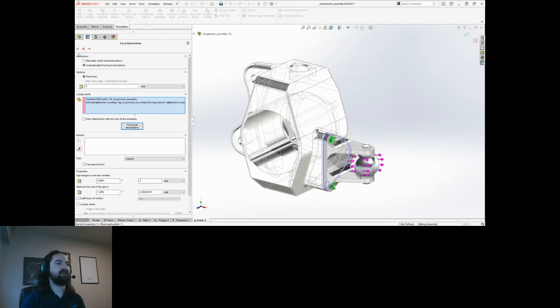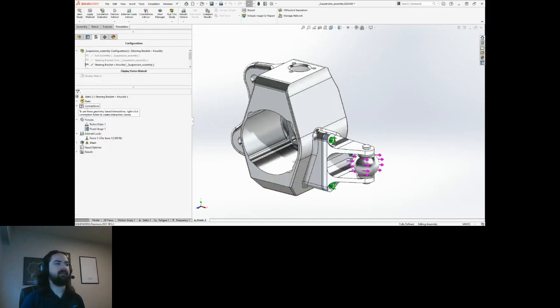All right, so I can go ahead and add that, and I can find it under my connections in my local interactions. There it is, that local contact interaction. Now, with this new interaction I've just created, it effectively does a better job than the slider fixture, but it covers the same bases, right?